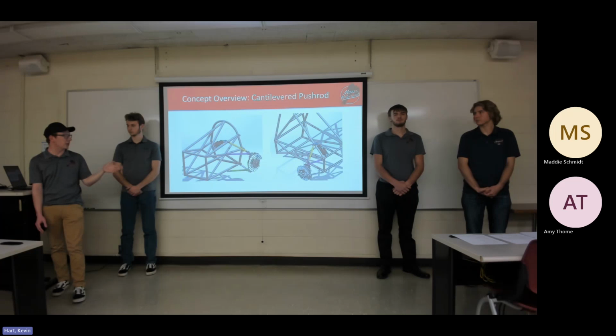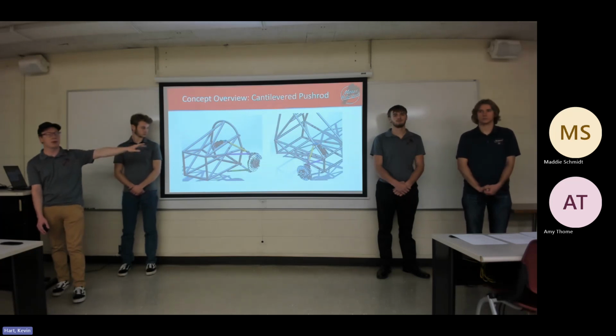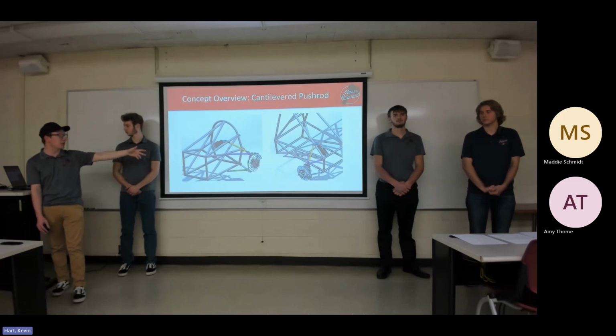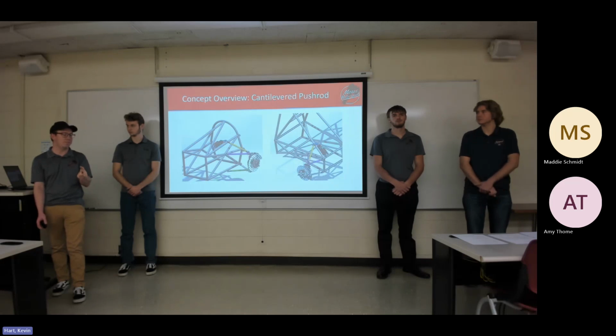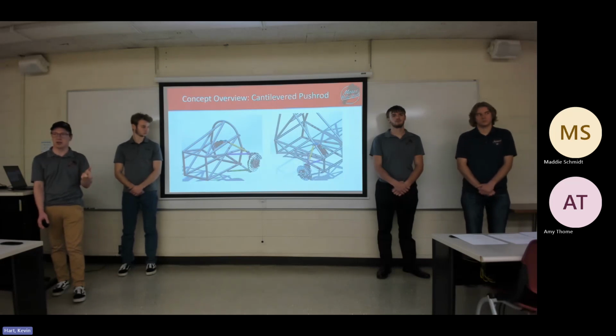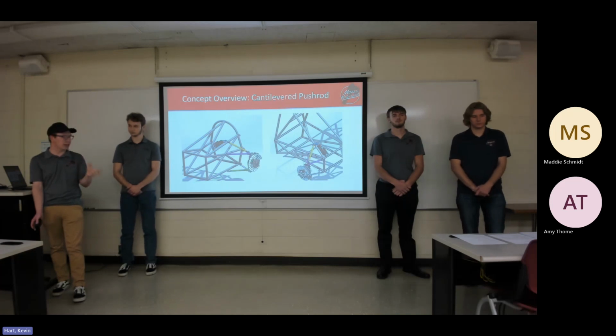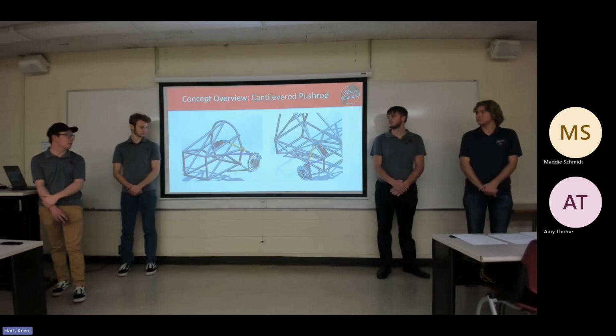Cons are the front packaging. We're going to have some electronics that go up in the front underneath this nose cone area, and having a shock there isn't as optimal as it could be. And then the other main con is the fact that since the belt crank is cantilevered through the frame, it puts a lot of torsion in the middle of that frame member, and then any compliance in the chassis is not great.